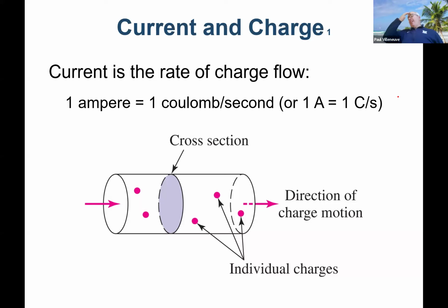And so you don't need to worry too much about the corona effect because the voltages tend to be so much smaller. So that's the biggest reason why bus bars outdoors will be round, and inside of a switchgear they're rectangular: it's for space and you don't have corona as much. Those are the two big reasons. Good question.